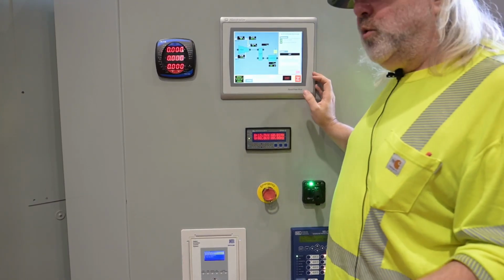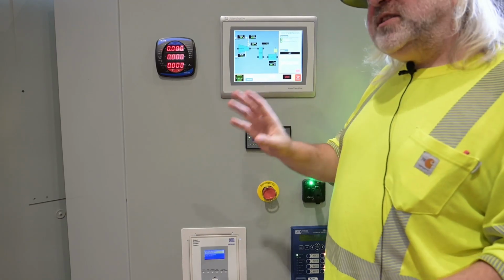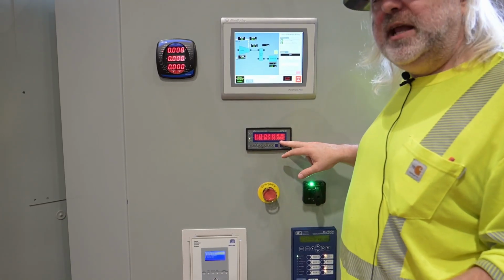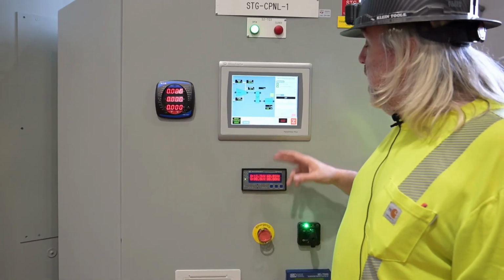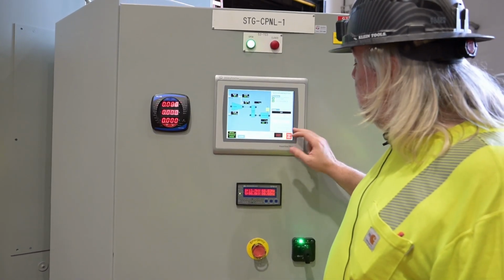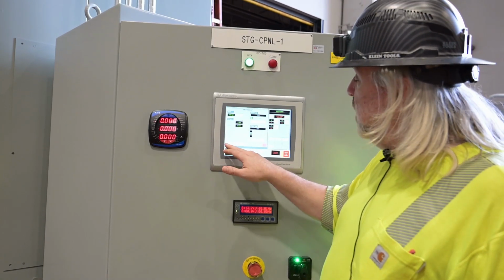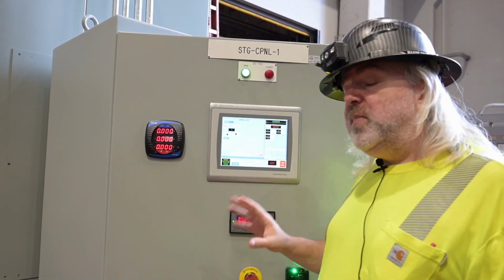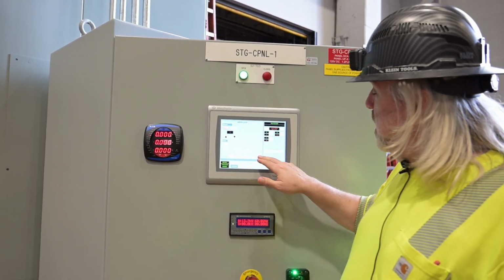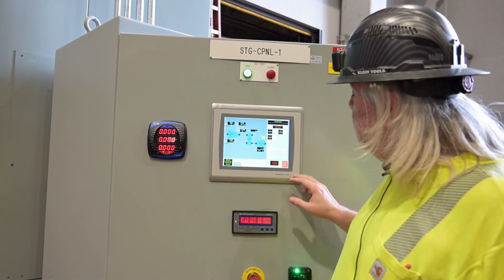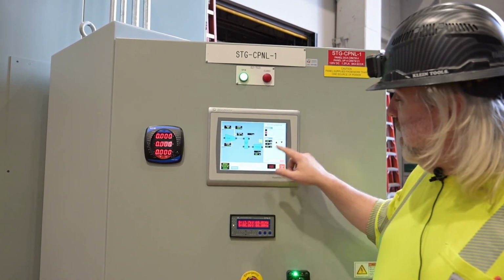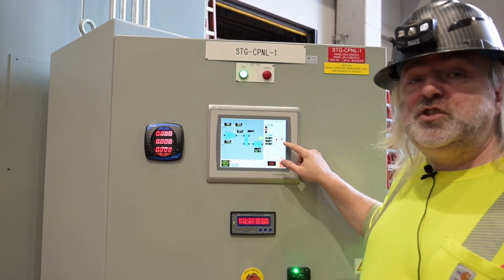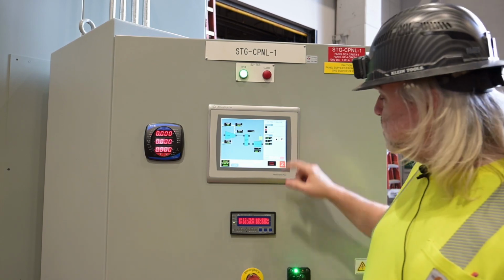If we select manual, at that point, you as the operator will be responsible for adjusting your voltage and your frequency to get to where you need to be. And again, our frequency can be adjusted by adjusting our speed set point. 1800 RPM is going to be 60 Hertz. Our voltage can be adjusted by moving to the voltage AVR button and then adjusting your voltage through these two raise lower functionality on the voltage regulator.